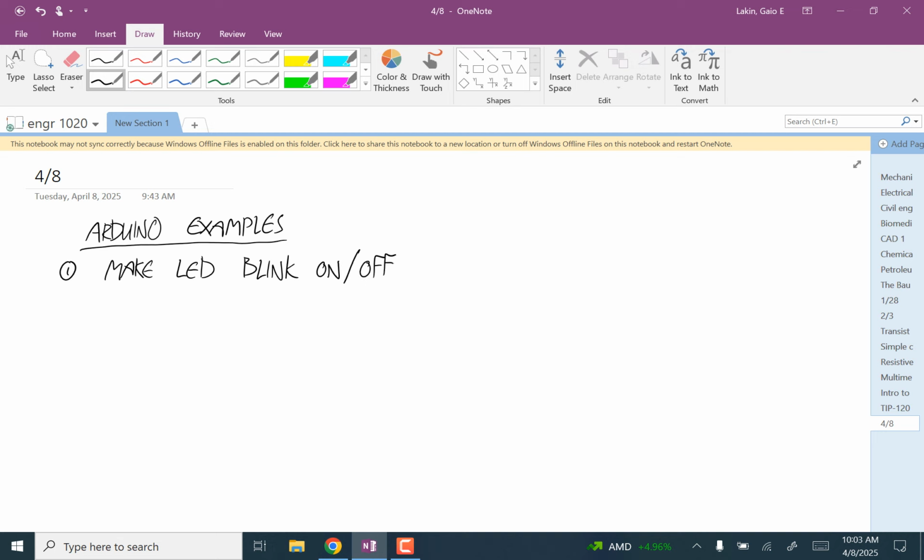I'm going to do this one first because the current that you need to make an LED go on is small enough that we can do this directly from the output pins of the Arduino board. Okay, so the way we're going to do this is I'll draw a schematic first. We're going to program a pin. For some reason, just randomly, I chose pin 8. You could do this with any pin. If you want to get crazy, choose a different pin. I'm not the boss of you.